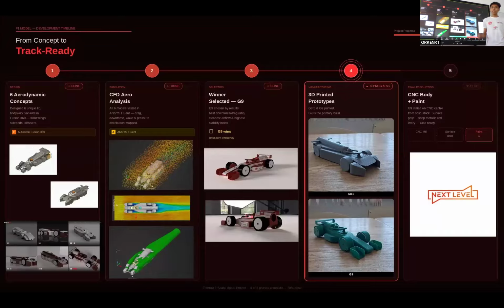At the beginning, we believed that a more complex design would automatically mean a better design. Some of our earlier concepts focused on aggressive geometry, internal airflow changes, and complicated body shapes. The idea was to control airflow by guiding it through and around the car. For example, in the G8.5 model, airflow was divided into multiple paths. Part moved underneath the car, while another part passed between the front wheels and the main body. The rear wheels were also partially integrated into the body to reduce turbulence.